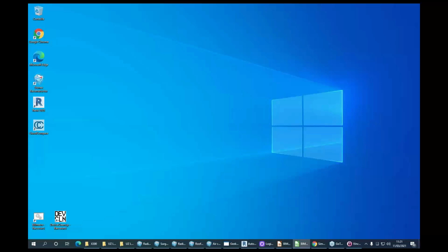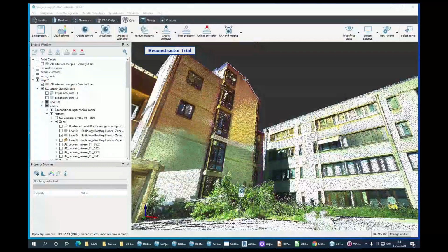If we are doing extremely long scans, obviously at the very far end of the range, the accuracy will be a bit less. It's not going to be 1 millimeter exactly there; it's going to be a bit more. If we have something that is here, it's going to be 2 or 3 millimeters. According to the data sheet, but from our observation, we almost always fit into 1 or 2 millimeters, depending on the type of surface.